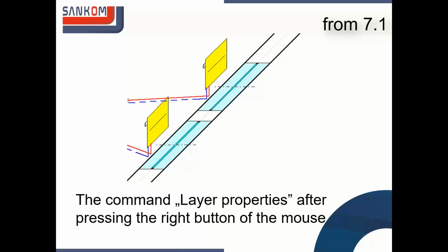And the other command, this is not really new, it has existed for ages, but now it's just in easier access. If we want to change, for example, by default, we suggest this yellow radiator, but you can choose another color. You have to edit the layers, because we use this layer technique like in probably all the CAD software. But we have about 100 standard layers, so to find the appropriate layer, it can take you a few seconds.